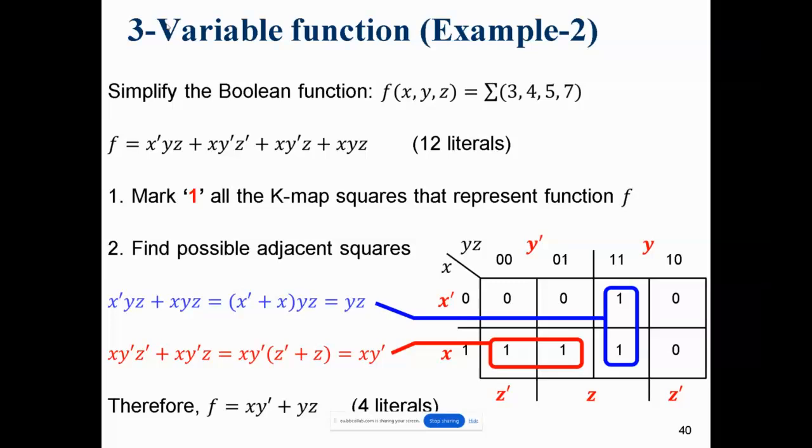This F is the sum of the minterm expression. This sigma is the sum of the minterm form. And this F is actually the reduced sum of the product expression. This is called a sum of the product expression. We do not have a sum of the product form for the other because it covers a lot of minterms. So the last one is the reduced, minimum possible sum of the product form. These are the definitions.